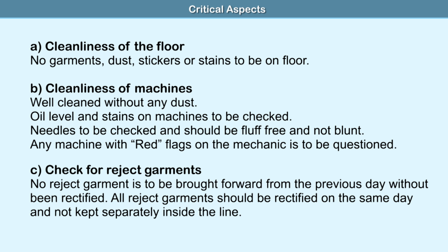Cleanliness of machines, well cleaned without any dust, oil level and stains on machine to be checked, needles to be checked and should be fluff free and not blunt. Any machine with red flags on, the mechanic to be questioned.